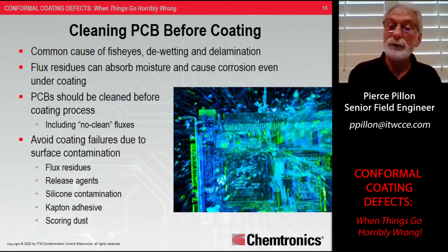And this includes no clean fluxes. And a little word about no clean fluxes. No clean doesn't mean you shouldn't clean. The reason no clean fluxes are called no clean is because the residues do not, according to the manufacturers, contain any ionic ingredients or ionic portions of that residue that can promote dendritic growth. However, no cleans, as well as a lot of other fluxes, can cause reactions with the coating and cause adhesion issues.